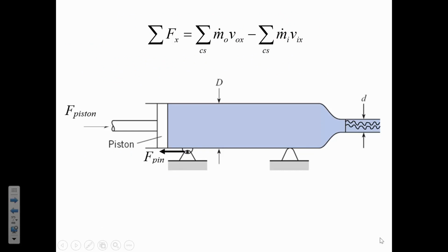In your assignment, you have this one. And this is water that's flowing out of a nozzle, but the pipe does not continue infinitely to the left. What's causing the flow outward is the fact that inside of our control volume, this syringe is pushing the fluid out. And so if you draw your control volume so that everything inside of this nozzle is inside the control volume, there isn't a P1A1 that's going to have to be added externally.